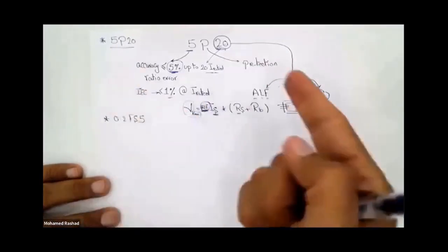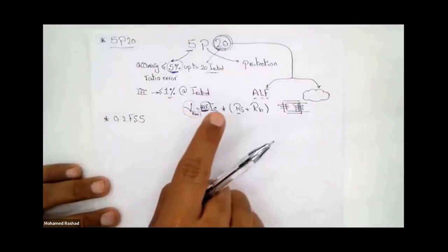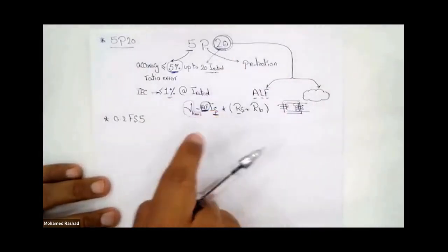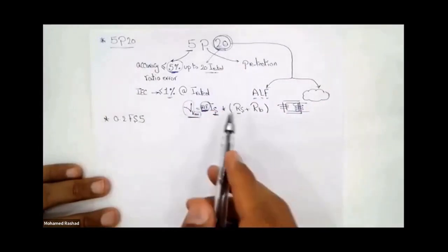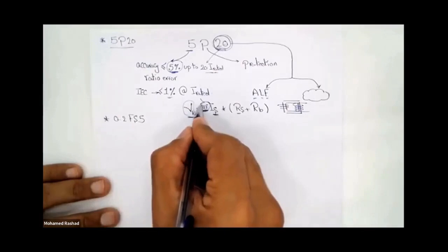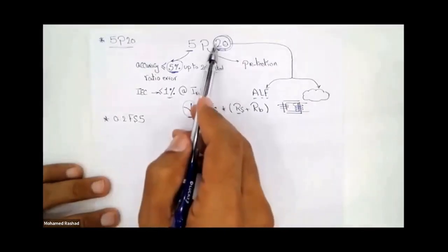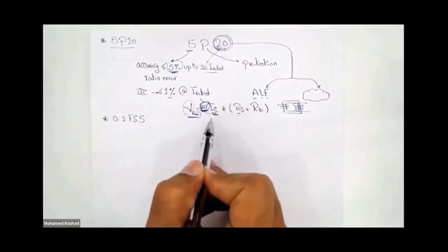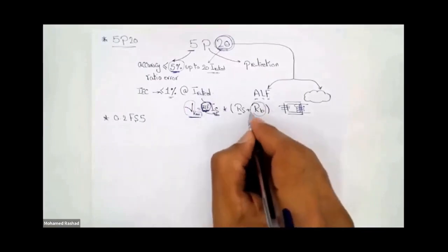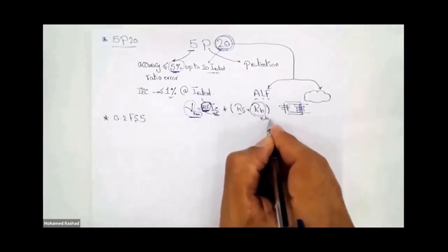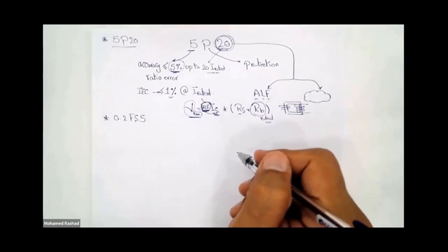And since I am a protection core, this factor tells me that in my manufacturing, I guarantee that your CT will reach the saturation stage, and the knee point voltage will be reached, at a number of times greater than the accuracy limit factor of I2, meaning greater than 20 times the current I2. But this is linked to the burden connected here, which is the rated burden written on the nameplate of the current transformer.